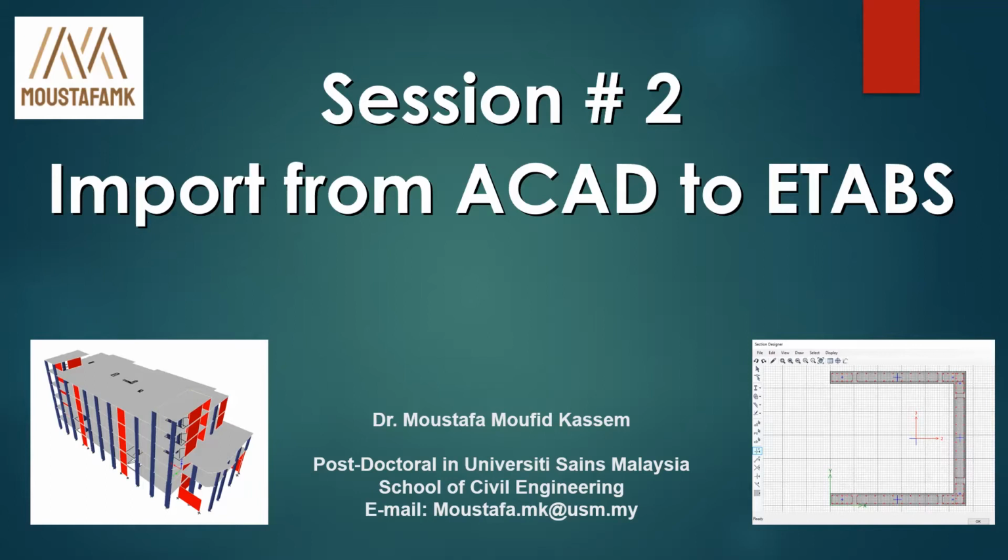So we need to convert the architect plan into a structure plan first. We need to focus only on the structural elements like columns, beams, walls, and openings, because in the architect plan, usually we see the column locations, but the beams are our responsibility.